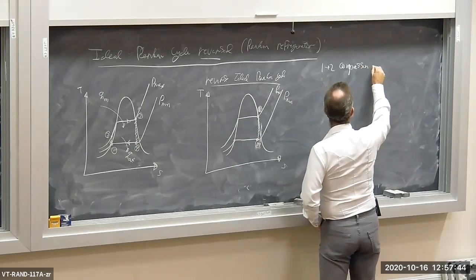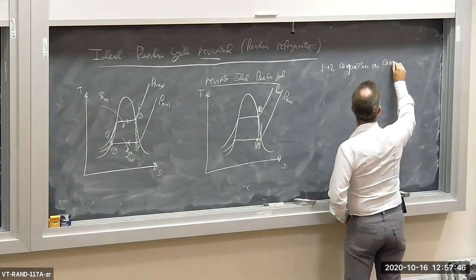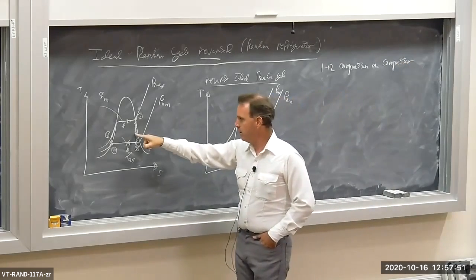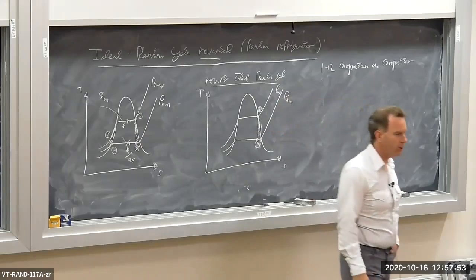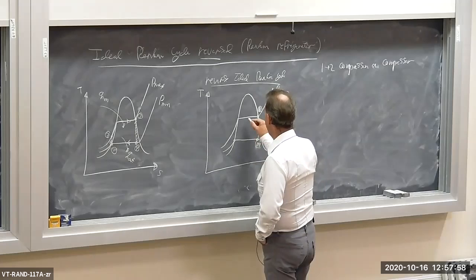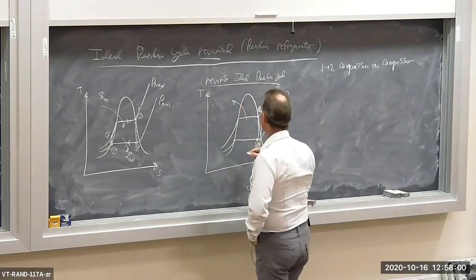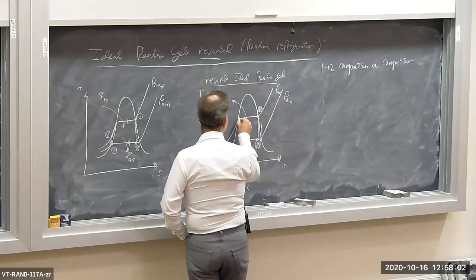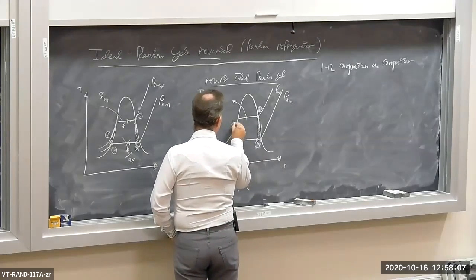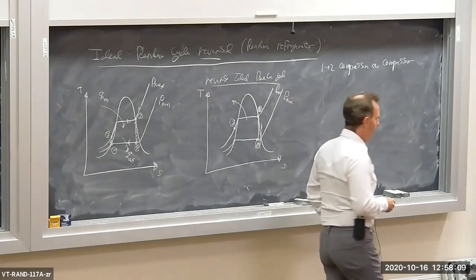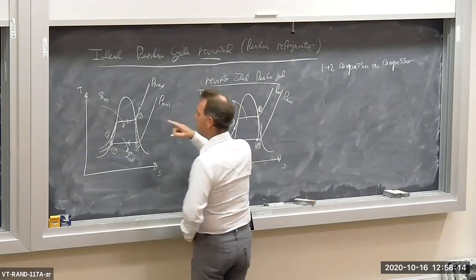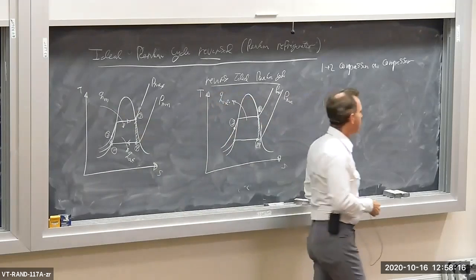So our turbine, 3 to 4, became a compressor, 1 to 2. Then we have heat rejection, constant pressure at high pressure, down to state 3. So we have heat rejection output, Q out. I'm just reversing the direction of the Q in, and it becomes a Q out.